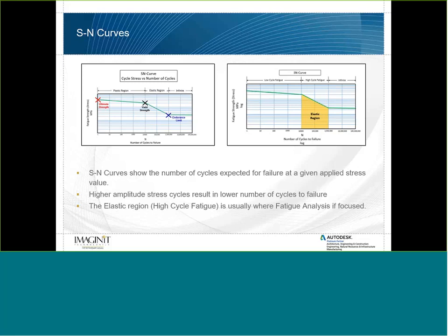Typically, the most important region for fatigue analysis, and the region that we will focus on, is this elastic region, which is also known as high cycle fatigue. So what we're looking at is maybe a smaller load, maybe not quite the maximum load, but a high number of cycles.